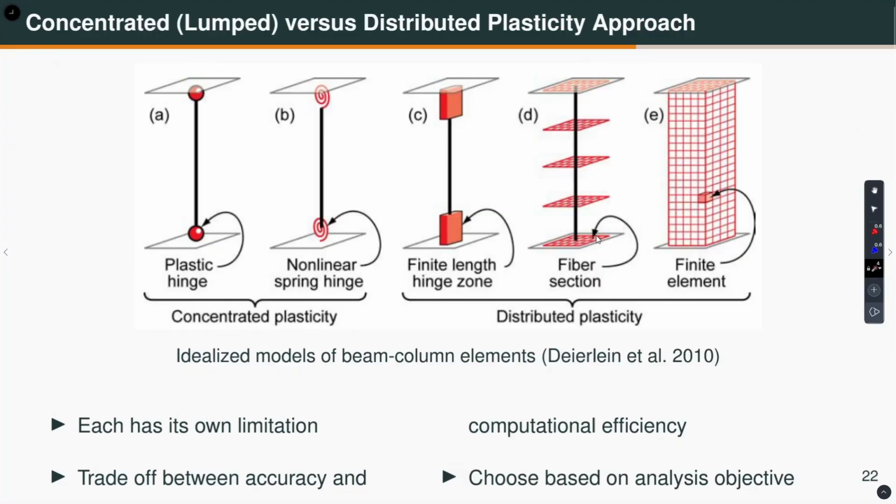So, you can define it, and that means the plasticity is distributed along the length of the element. So, this comes under distributed plasticity. And you can also do a continuum model of an element which looks something like this. What is this? Well, this is kind of, you can say, a hybrid where the plasticity is spread over a finite region at the end.